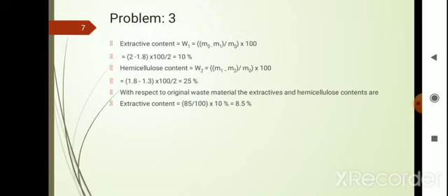So it will be 8.5 only. So if we are considering moisture also, this value is reduced because of the 15% moisture. So only in the remaining 85% do we have extractive, cellulose, hemicellulose and lignin. So we have to multiply the obtained value by 85 divided by 100.